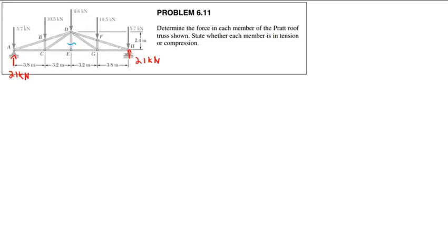Again, up on this joint here, this thing's really complicated, but that doesn't matter. All that matters is if at one end a member is zero force, then at both ends it must be zero force. Either end can make a member a zero force member, yes. So is FG zero as well, and BC zero? FG, is that one zero?